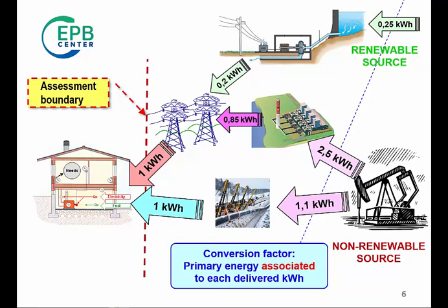There are two possible reasons for the difference between the amount of delivered energy and the corresponding amounts of non-renewable primary energy and renewable primary energy that are taken from the sources. One possibility is a conversion efficiency, for example in a thermal electric plant. Another possible reason is losses in a grid, for example in the electricity transport and distribution network.